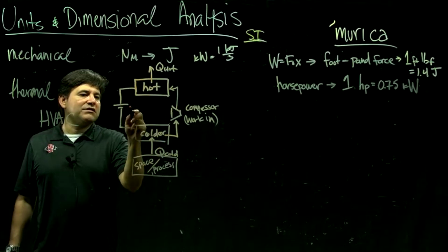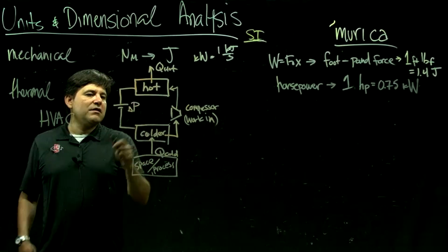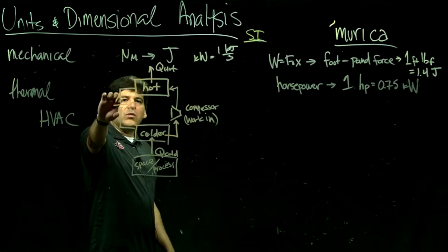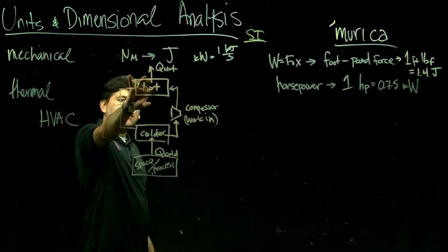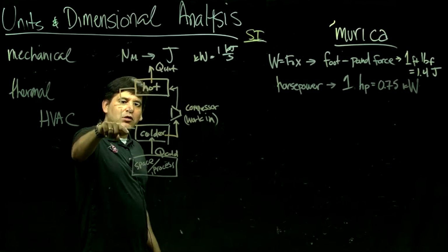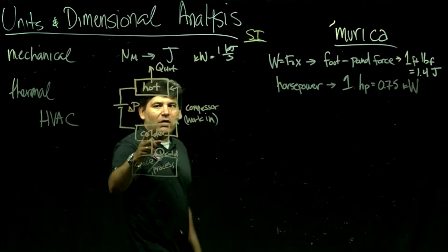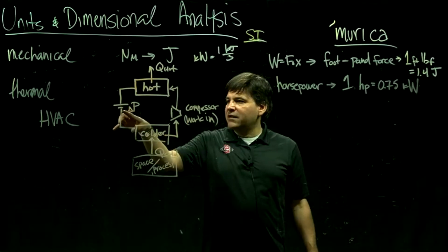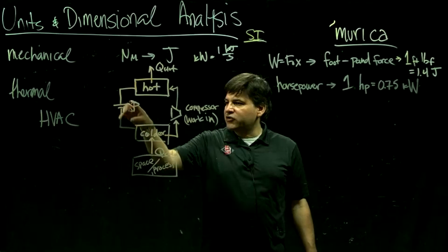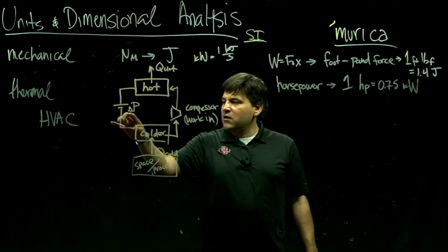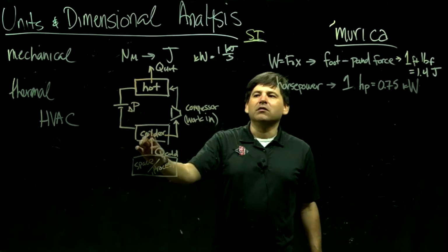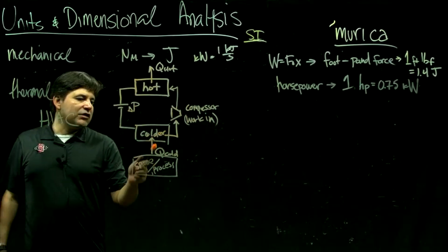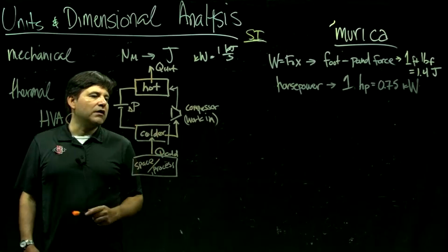And a big part of this too is there's a big pressure drop, and this gets sprayed through a nozzle. Once you have a high pressure refrigerant and you spray it into a low pressure, it gets really cold. That's how it works. The mechanical work brings it to high pressure. Then you expand this through some nozzle to give a big pressure drop from high to low pressure. Once you do that expansion, it gets really cold. The refrigerant gets cold when you do that, and that allows you to go from cold to colder.